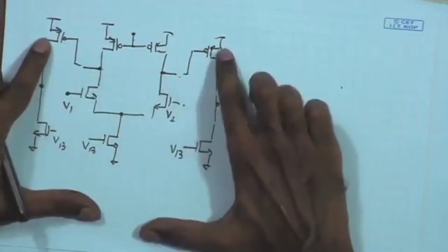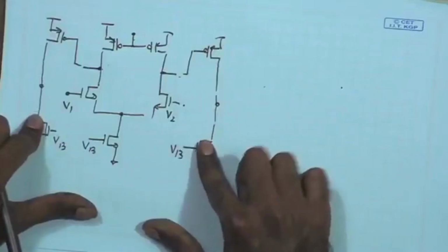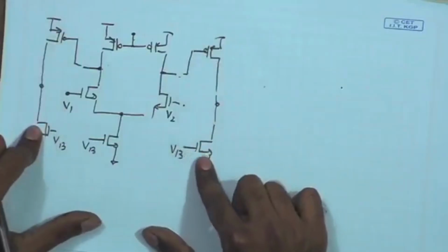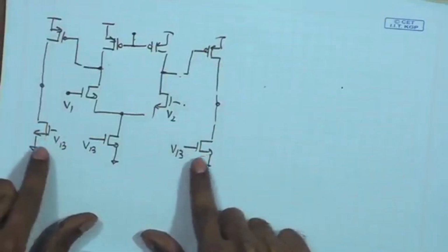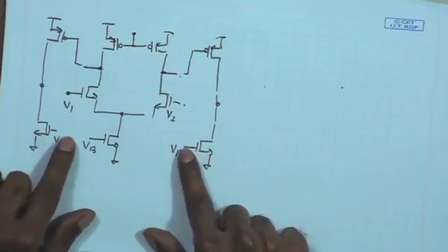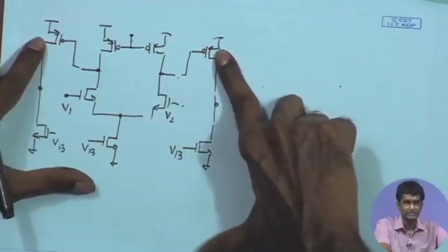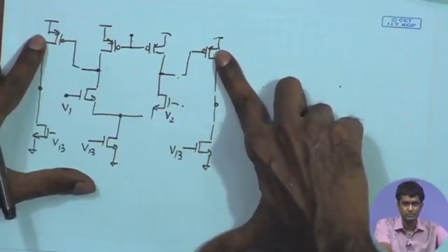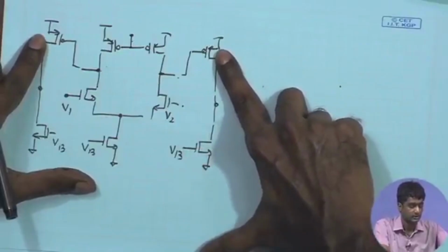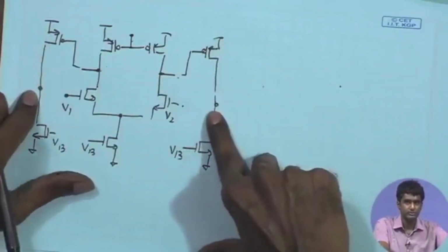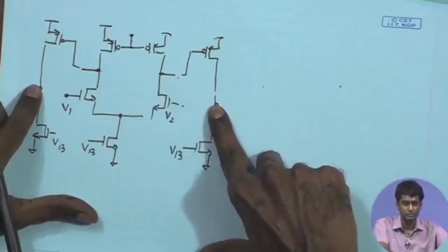After that, you have just another common source stage. These 2 transistors are providing another common source stage where these 2 bottom transistors are active load. They are biased with a fixed DC potential, providing active load, and these 2 are the input devices of the common source transistors. Therefore, these 2 stages are also going to provide a similar gain factor Gm RO by 2.